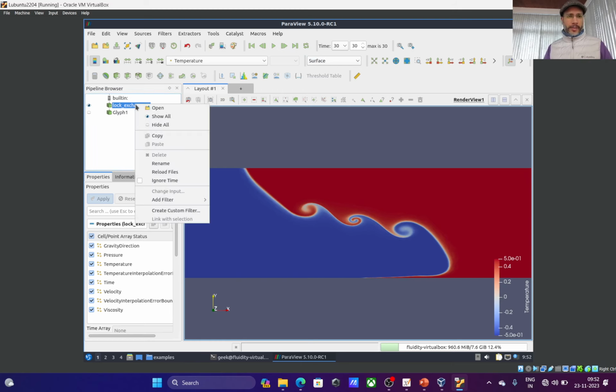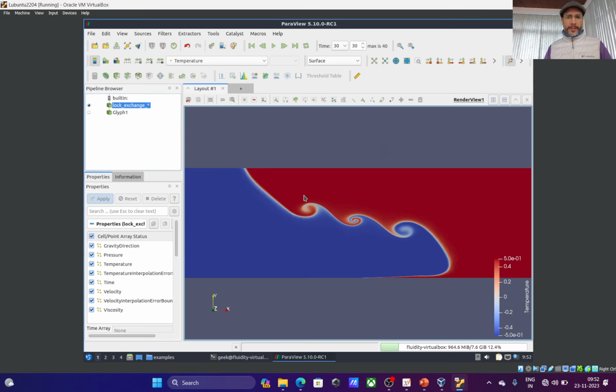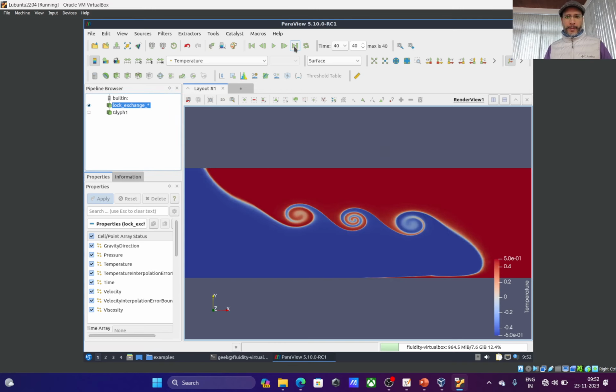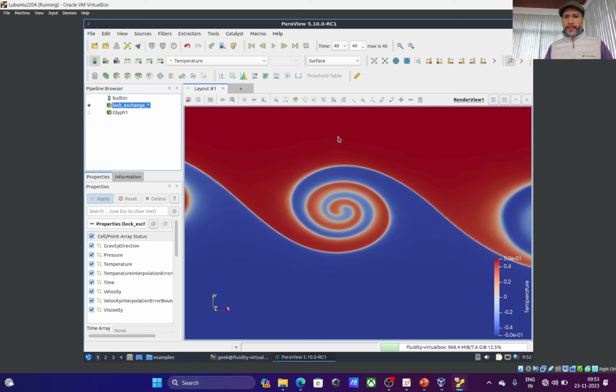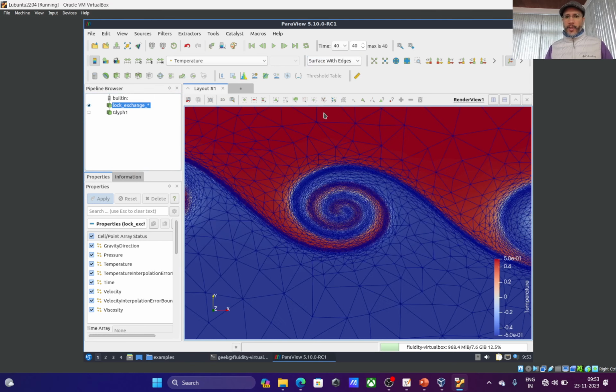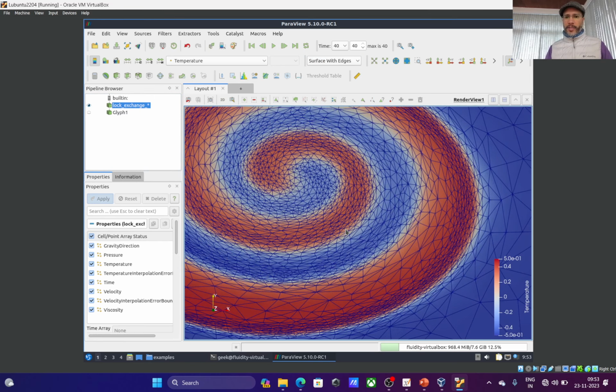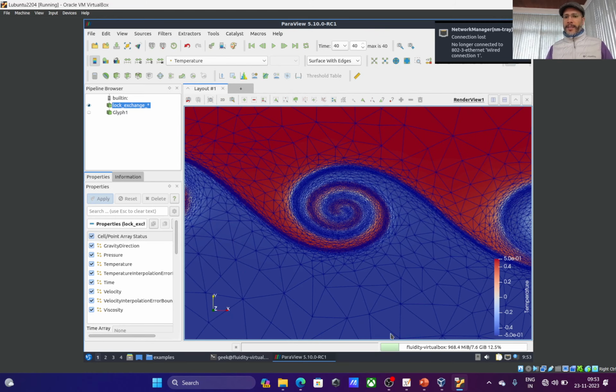So we can actually reload, it should have completed. And this is because you have a very large number of mesh elements in this region. But in the region where nothing interesting is happening, it's very coarse. So this is called adaptive mesh refinement or mesh adaptivity. You adapt the mesh based on solution values. So with FEM, you can actually do these things very efficiently.